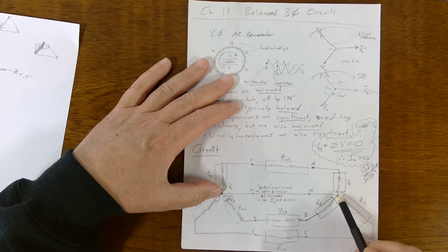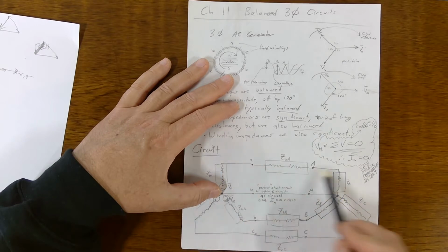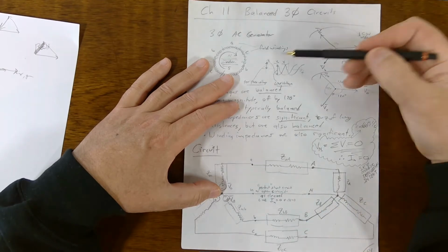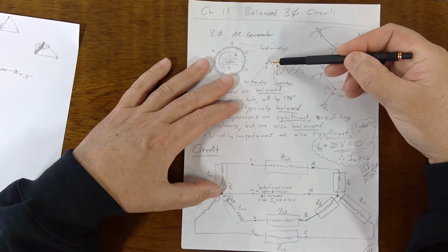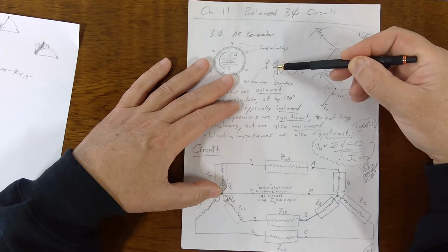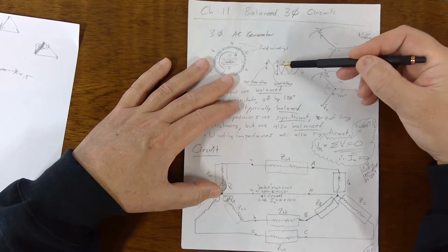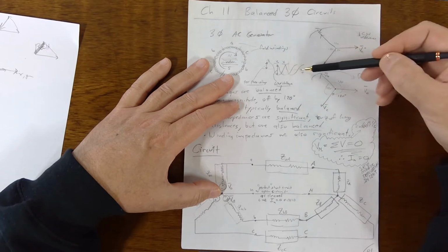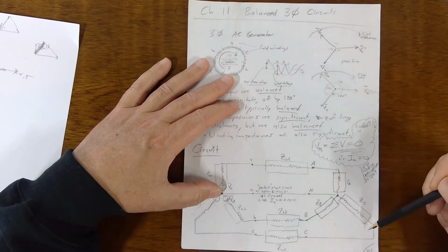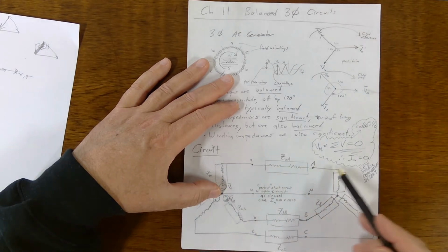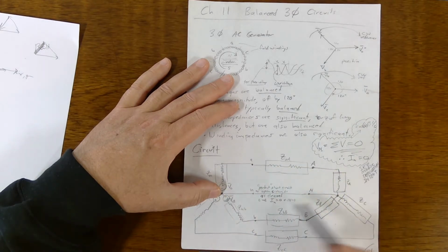So how's the current getting back, right? The current starts here, goes up around. It has to get back. It gets back through these other phases, one of these other phases, one or both, right? Look at this up here. If VA is positive at any given time, at least one of these other 2 phases will be negative. At least one of them. Maybe both. Depends on where you are in the cycle here. That's where the current will go. Okay, so it'll come up around here. It'll come back to this 0 point. So it won't go this way because there's no voltage potential to push it that way.